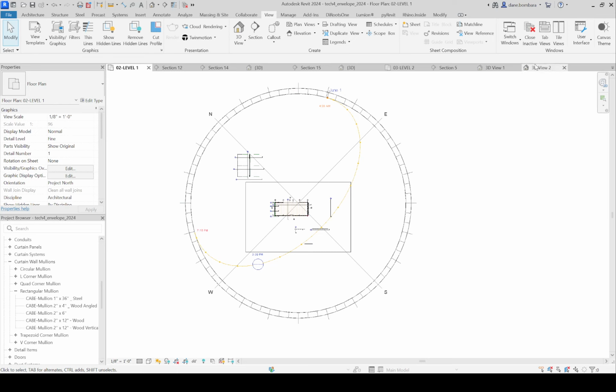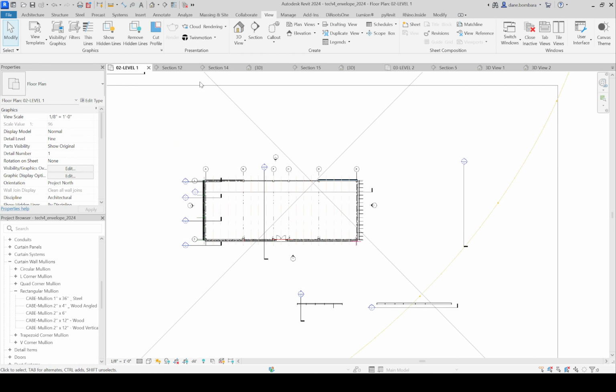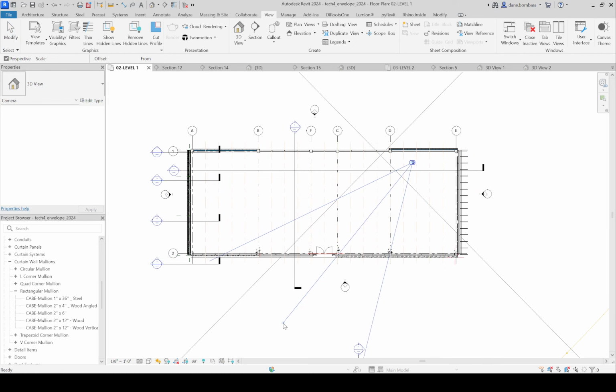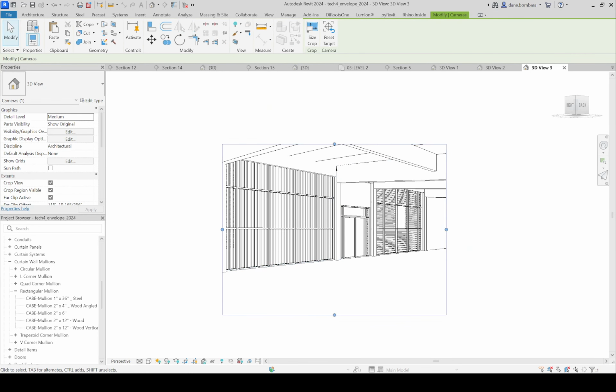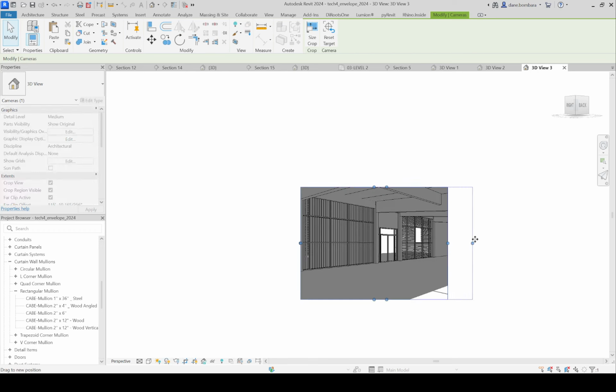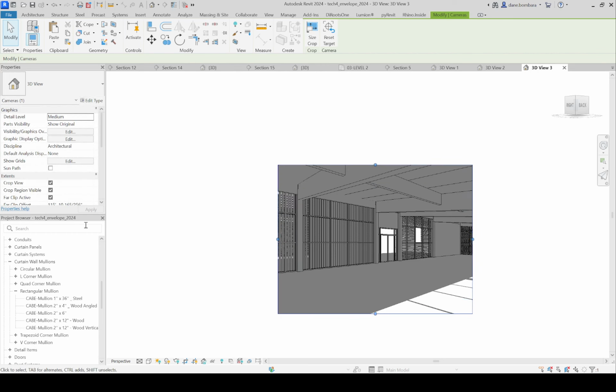So I'll just say this, when you create interior views, I'll create a new one for a second. In a plan or whatever view, do this exact same thing. You go to 3D view, I take a camera, I drop my camera, I look in a direction, and now I'm looking that way. If I want to see shadows, I have to turn them on, which is the button next to the sun button. We'll turn the shadows on. The shadows are a little overbearing, so I always adjust the graphics a little bit.